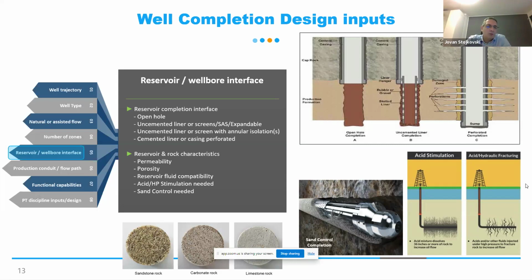Because if we have a very consolidated rock, most likely we need some sort of stimulation, acid or fracturing job. And this will dictate the shape of the well through the reservoir, meaning the well path.